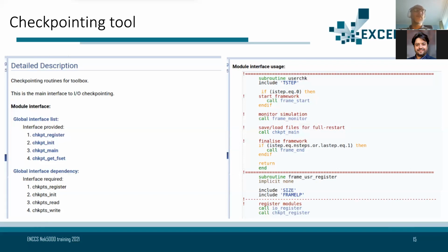And in most cases, it doesn't matter, because the noise you include in the case is not enough to start an instability. But we found a pretty nasty and sensitive jet in the Crespo case, where this was breaking the whole simulation, and it was not possible to perform it. That is why we have, for example, a full time restart procedure, our checkpointing, which keeps the order of time integration during all of the simulation after the restart as well.